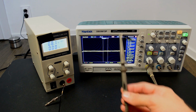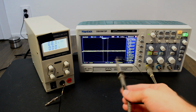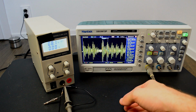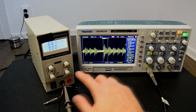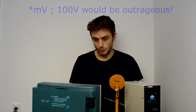So this is the noise that my oscilloscope generates on its own. So right now my probe is connected to the ground lead and I'm reading about 8 millivolts of ripple. So this is quite okay for this type of cheap oscilloscope. Now watch what happens when I connect this thing to my power supply. So I'm only connecting this to the ground input, so not the signal input, and I'm getting more than 100 volts of ripple, which is, quite frankly, unacceptable, especially if you're trying to make low noise measurements.